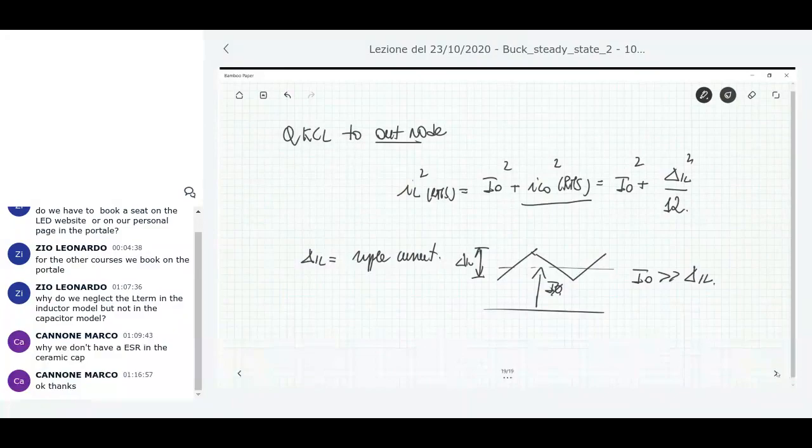And this is a parameter that leads to some drawbacks, because it leads to overheating of the capacitor, so it shortens the life of this capacitor, etc. So in order to get less stress in the output capacitor, for example, delta IL should be very low, should be minimized. And delta IL is the same as the ripple of the inductor current. Then I will show you next time another reason why I want to get delta IL very small.